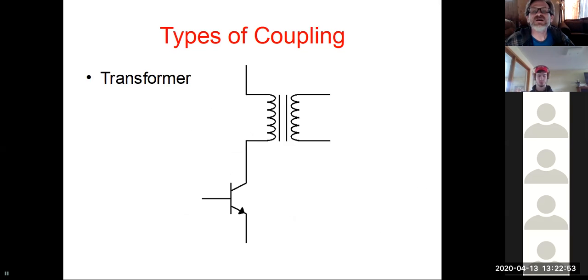All right, go ahead. And here's a transformer coupling directly in the collector, but there is no tuning for this. So if you see the two open ends on the right-hand side of that transformer, and you hook up some device to it, it's literally going to transmit that signal directly through without any kind of filter. So if it's a noisy signal, it's going to pass right through, if you will.